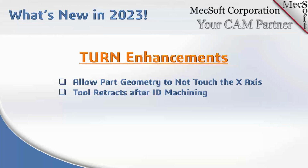Now, that really caused some problems when you're parting off on the back of the part. If you don't have enough part material or stock material behind the part, it made it impossible or difficult to do the cutoff, the part off operation, in the back. Now your part can be offset out from the x-axis, and it'll automatically compensate for that when it defines the part geometry, which makes it a lot easier.